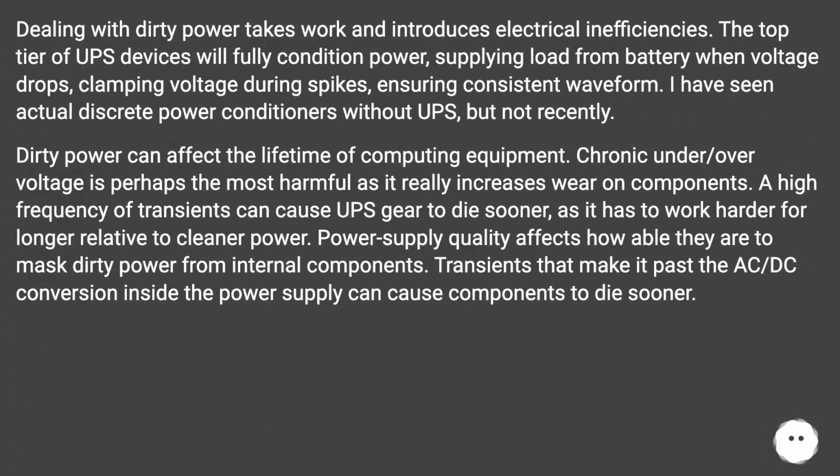Dealing with dirty power takes work and introduces electrical inefficiencies. The top tier of UPS devices will fully condition power, supplying load from battery when voltage drops, clamping voltage during spikes, ensuring consistent waveform. I have seen actual discrete power conditioners without UPS, but not recently.